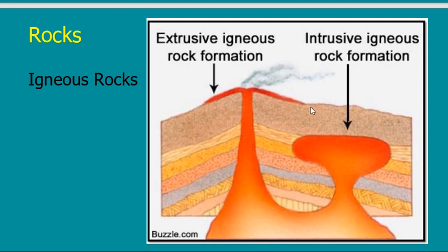If I do a site investigation and I reach rock, then I have to define the type of the rock. Is this rock igneous or sedimentary or metamorphic? If it is igneous, it is not enough for me to stop. I have to penetrate deeper.